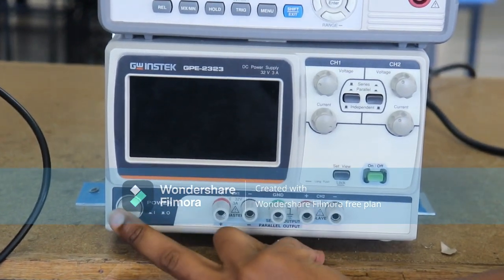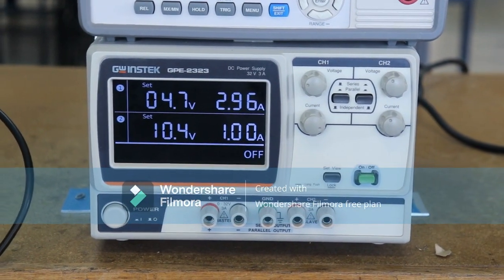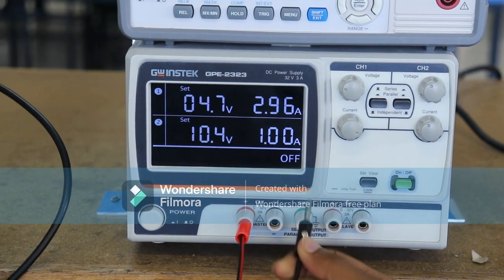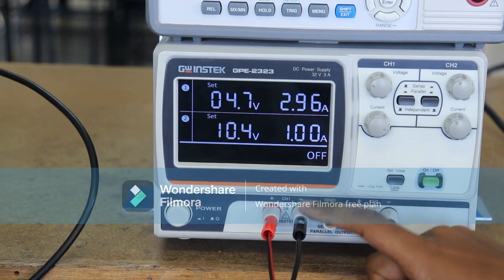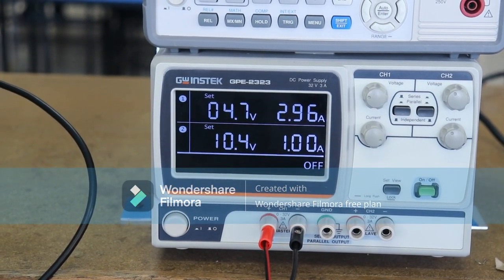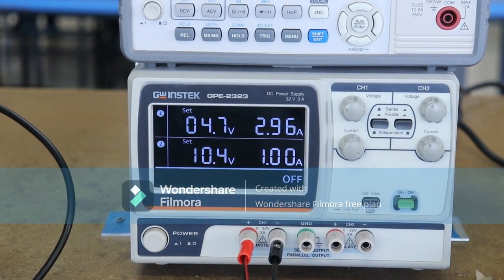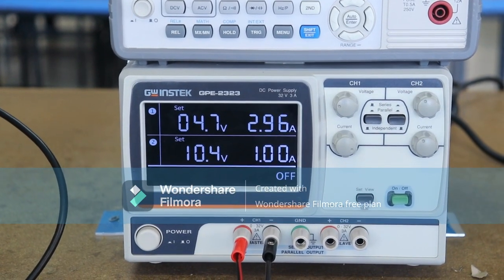If we look at the power supply, it is a fairly intuitive machine. How we would power it on is simply pressing that power button right there, and we'd be connecting up our terminals into the positive channel and negative channel of the power supply. Red goes onto the positive and the black one goes into the negative terminal. For this demonstration we're just going to be looking at channel 1, but these 2 channels are quite similar, so if you understand one you'll understand the other one.